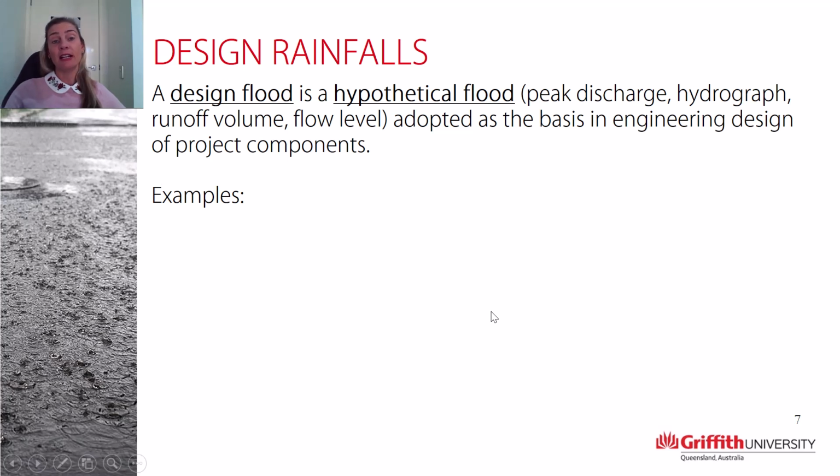So what is design flood? A design flood is a hypothetical flood, which can be either a peak discharge, a hydrograph, a runoff volume, or a flow level, which is adopted as the basis in engineering design of project components.